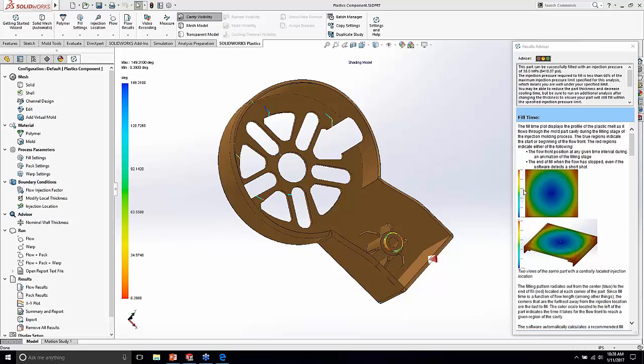So it is a trial and error. It allows us to go through and fully understand what we can adjust or what we can manipulate. But it's to give us a full understanding of exactly what's happening in that injection process so that when we get to the machine and we're about to inject it, we know exactly what's going to happen, or we have a fairly good degree of confidence of what the result's going to look like. So if we're going to receive things like short shots, right? If we have wall thicknesses so small that we're not able to inject it quick enough, this will help us to determine if a short shot's going to occur. The software will actually stop mid-solve for us and say, hey, I was not able to fill the volume for you. This is what it's going to look like.